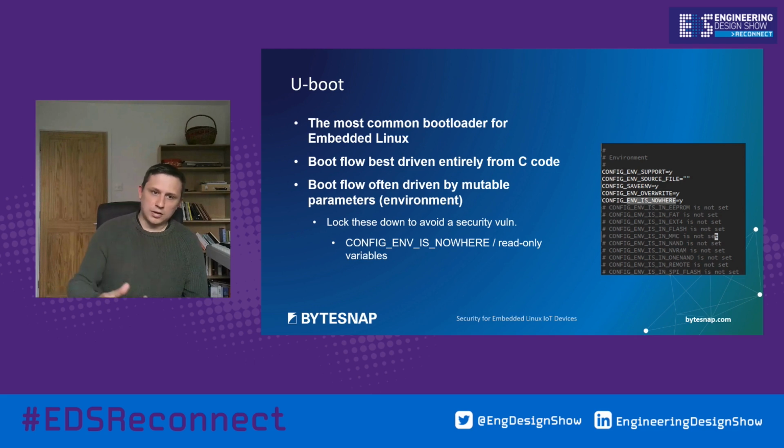Another issue is something called the U-Boot environment, which, like on the Linux command line, is a bunch of key value pairs, and these often define the boot flow. For example, where to load the kernel from, what boot arguments to pass to the kernel, where to load the device tree from. And again, great for development, but not so good for security. By default, they're just stored with no encryption, just on flash. So you might want to lock these down to avoid a security vulnerability.